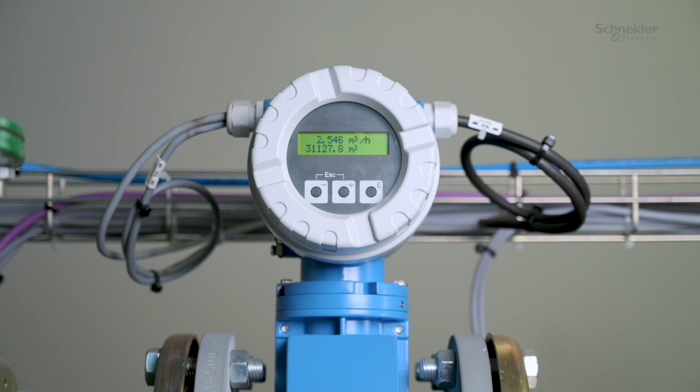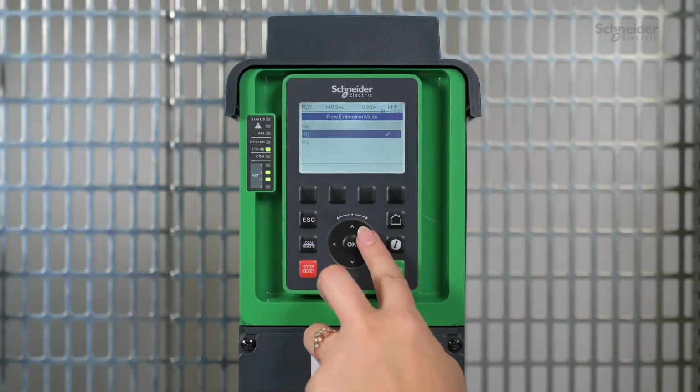When using the HQ curve in a multi-pump system, you must calibrate each pump individually. To calibrate a pump, you must isolate the pumps that are not being used. Calibration may be done using a global flow meter during commissioning. It will likely be necessary to recalibrate over time, as characteristics of the pumps change during operation. For our example, it is connected to the analog input AI3 and assigned to the system flow value. Calibrate the function with the following parameters.